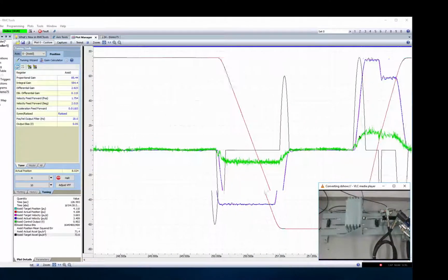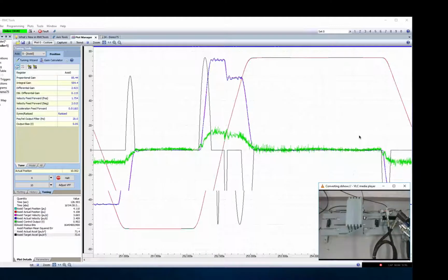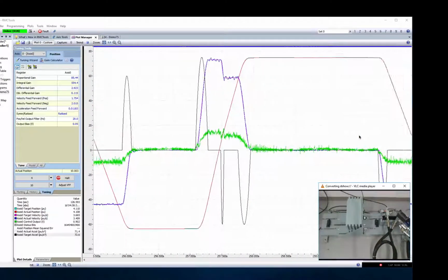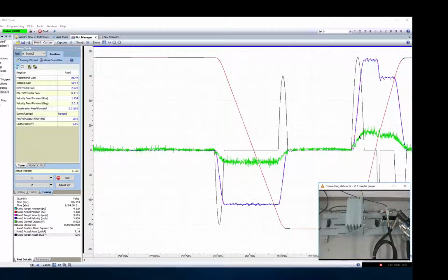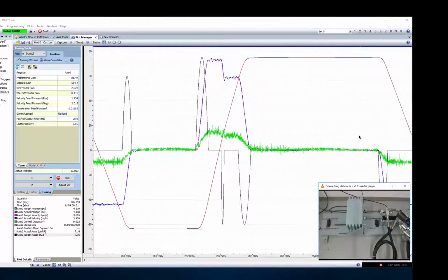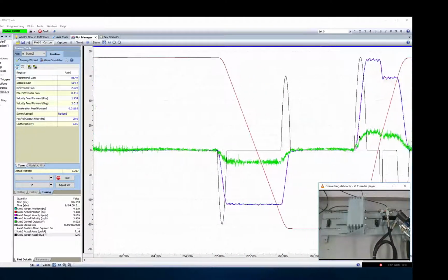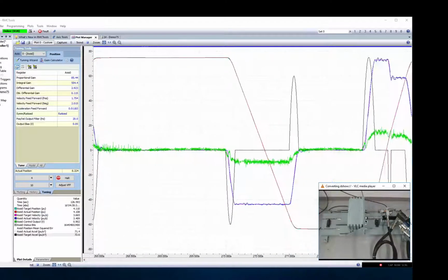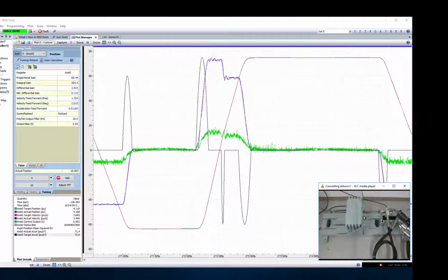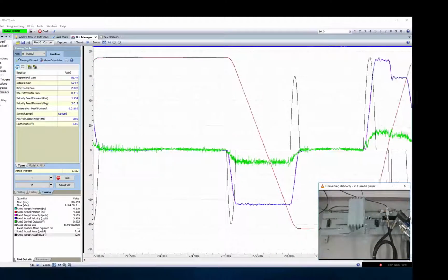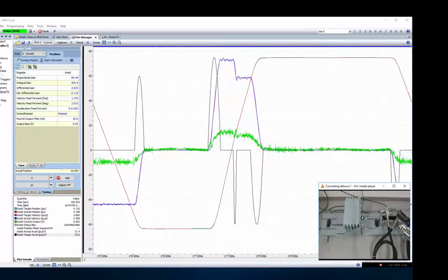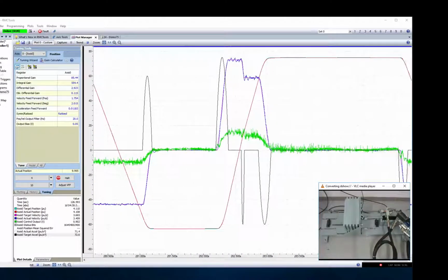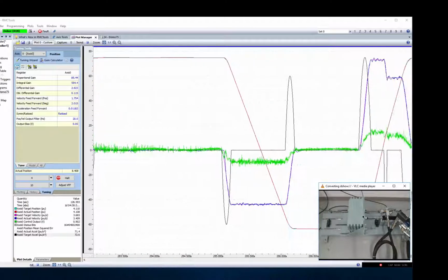This is a demonstration of Delta Computer Systems second order control and how we can reduce the need for having a high ratio of the natural frequency to frequency of acceleration. Below you can see a 300-pound mass being moved by a 1-inch diameter cylinder. This is not the way to design a system. The diameter of the cylinder is purposely designed to be too small so that the natural frequency is about 6 hertz.